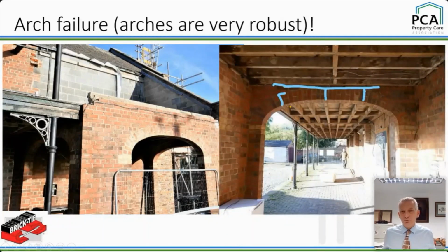The cracks don't show up on the photograph from this distance, but they're severe. And this is all now in tension. It's not in compression like an arch should be. It's got tension cracks in it, and it could drop out. We've had to fence it off. And it's happened because there's more thrust there. There's a very narrow abutment here, but it was coping well because it had the weight above it, holding down, driving down that load path to the earth, to the center of the earth, right?